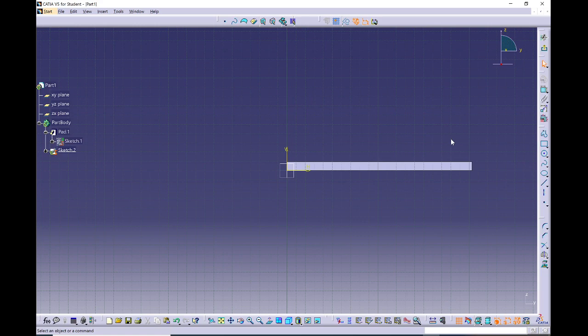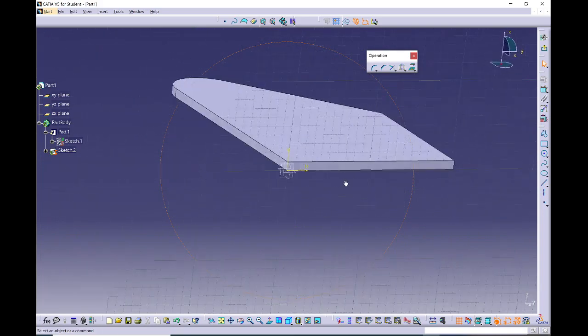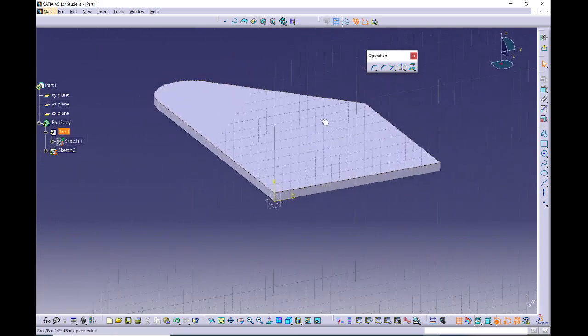Okay, one thing that you may not be aware of is the project command. Looks like a floating textbook. So let's take a look at this toolbar, the operations toolbar. Okay, so we can project onto our plane sketch, which is a 2D, right? Let me rotate slightly just to show you that I can project anything I want.